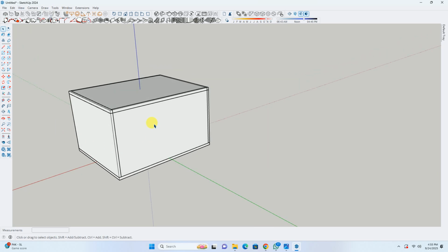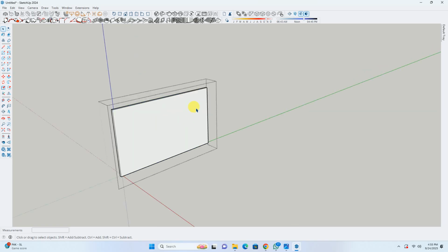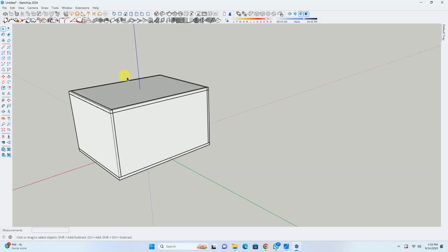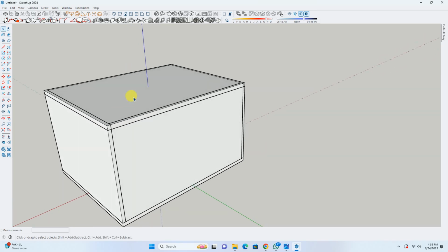Now when we double click on, or go to a group editor on any object, only the object of that group will be visible. All other elements will get hidden. But when we move out of the group, all other elements will become visible by themselves. By this feature, we can easily work on individual components.